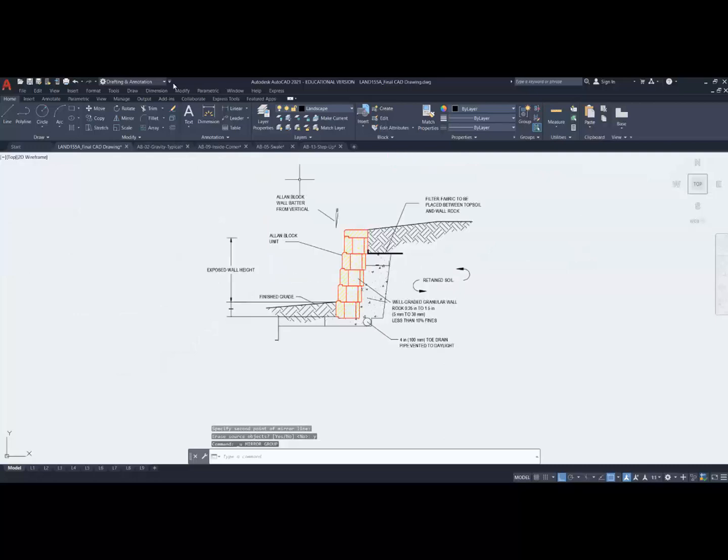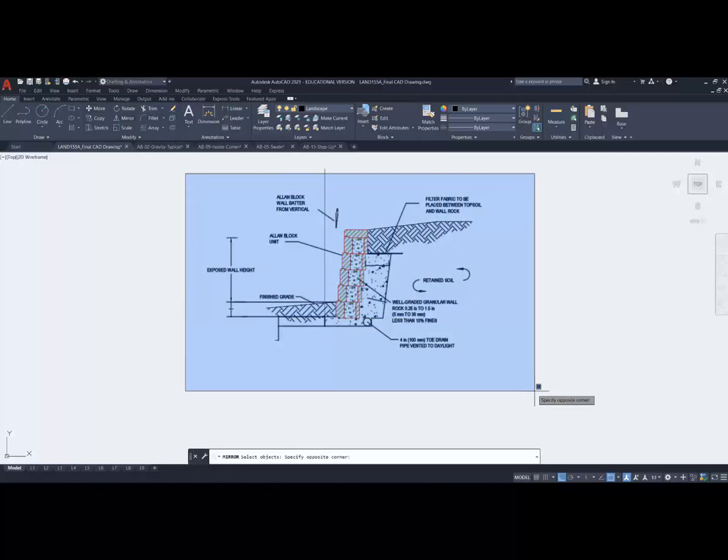Okay, what's a safer bet? Make your own line. So I'm going to click on a line from the footing straight up. I've got my F8 key on, and that's going to be my mirror line. It's just a way of assuring stuff. You can see how easy it is to make a mistake.